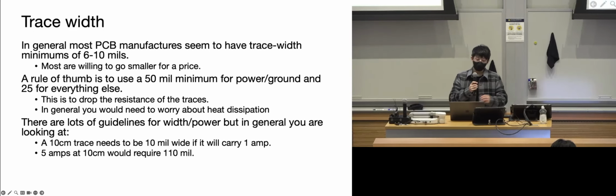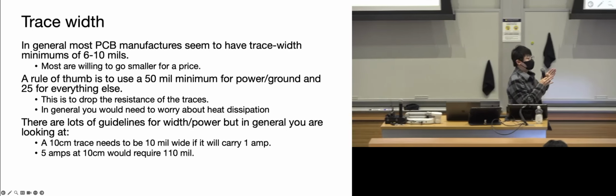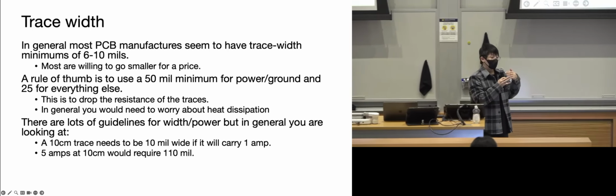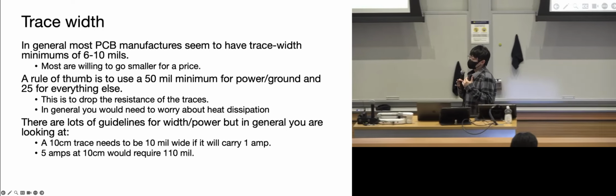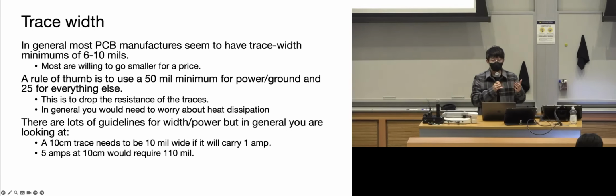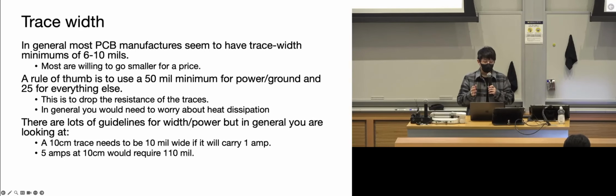It's also possible that there is some additional capacitance built up on your circuits, and that's usually because the wires on your PCB might be too close to each other and run together for too long. So you have this interconnecting capacitance built up, and that can slow down your signal transition as well.